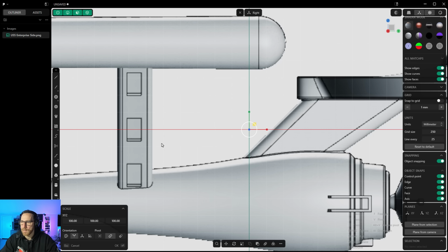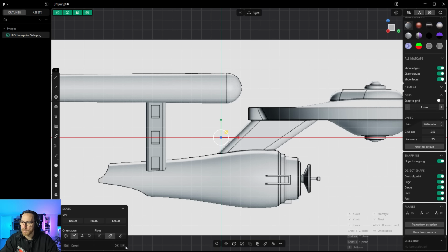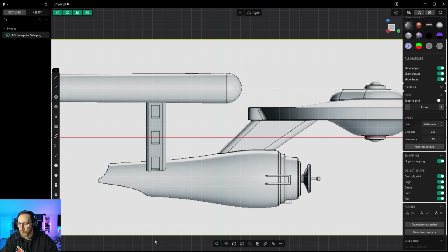While we're on scale, we can actually switch to the move command. Instead of hitting OK, we can switch over to the move command and move the image. And this is where the benefit of understanding the shortcut keys comes in. For our purposes to get started, I'm going to hit OK. This is either click OK, hit enter or return, or right click will confirm if you're using the default Plasticity navigation. And then with the image still selected, we're going to use move.